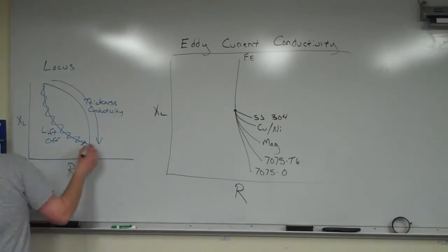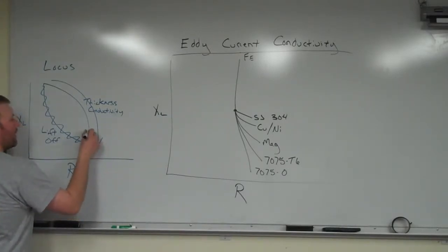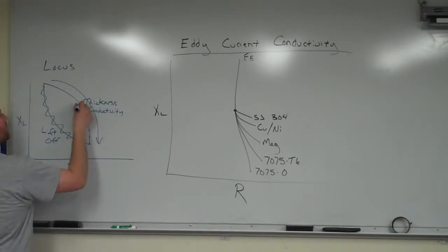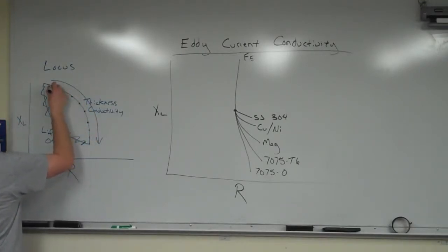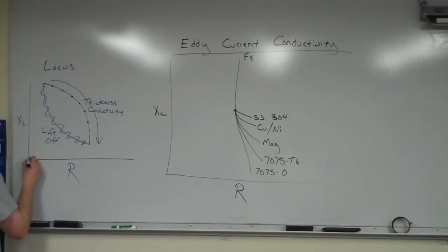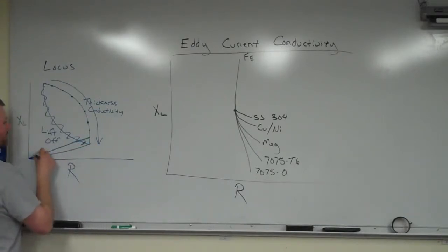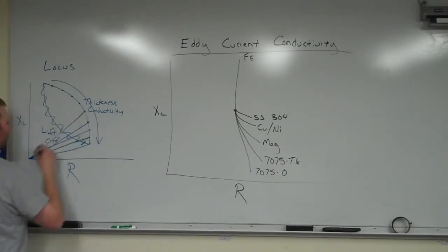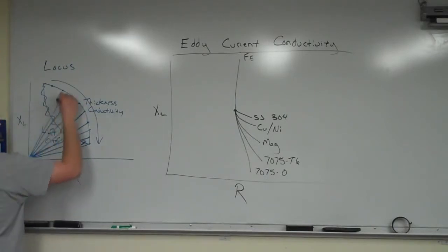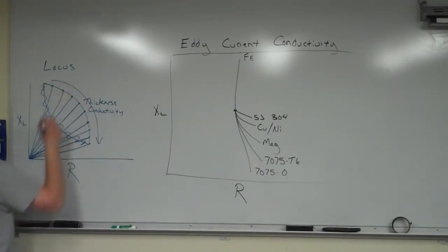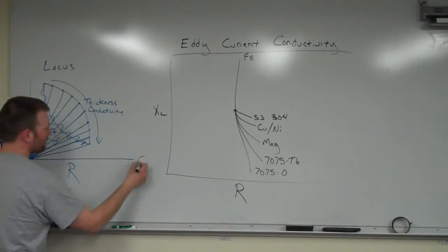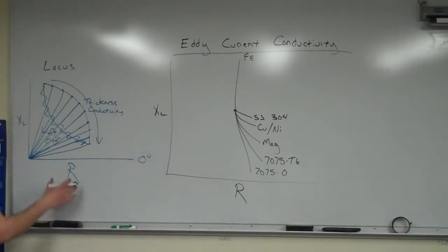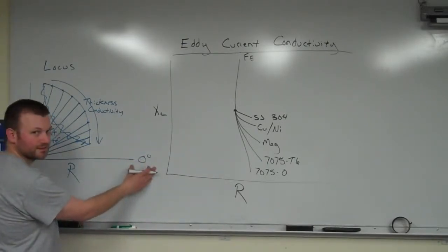We know that any point on this line, which we've seen already from the videos in Eddy Current 1 and all the other material you've been reading, is a different impedance point. That impedance is made up of inductive reactance and resistance, but we're basing everything from this bottom left corner: in a circuit carrying only resistance, phase lag is 0.